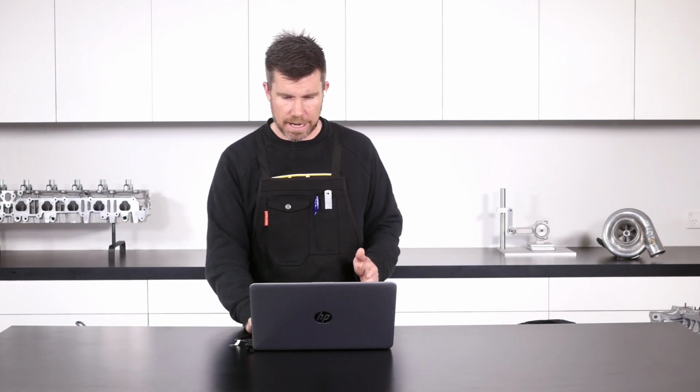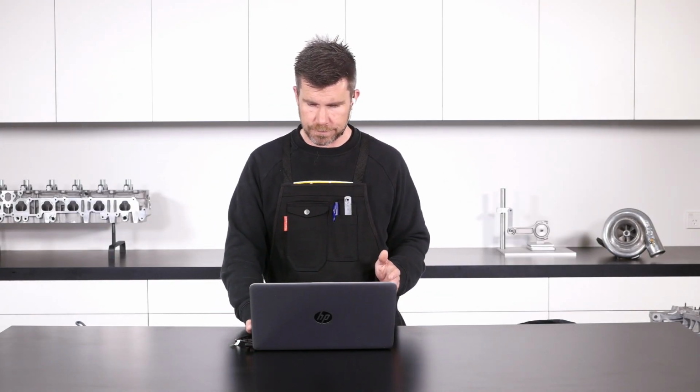Generally, we're going to do this on some stainless steel tube or maybe some copper tube, and we want to basically extend this a reasonable distance, maybe about 300 to 500 mil of that tube. Generally, we can also coil that up into a loop, and that helps remove the heat out of the exhaust gas before it reaches the sensor. So I'll just show you a couple of photos if I can.